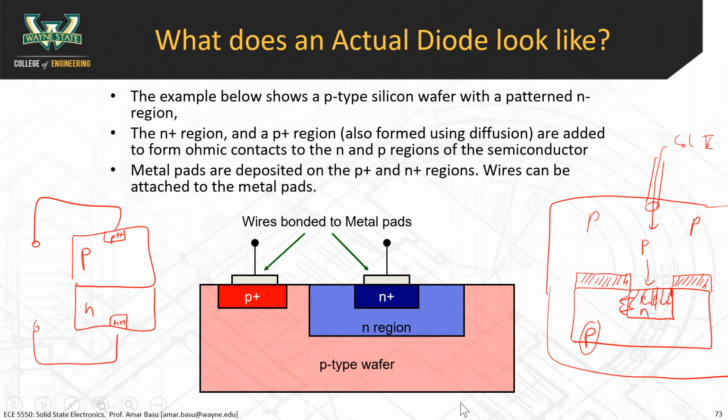And where is the diode? Well, when we drew the theoretical diode, we said that this is the area of the diode. If you imagine this as a three-dimensional device where you have the P-type and N-type material together, the area of a diode is everywhere that P-type material intersects or is touching the N-type region. So in a diode that's made like this, the area is here, on the bottom here, like this, and here. The area is actually on all sides of that N well.